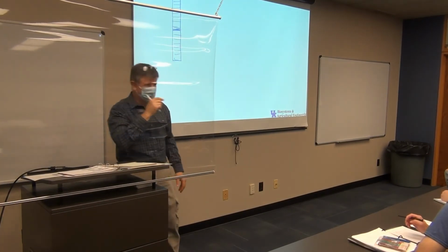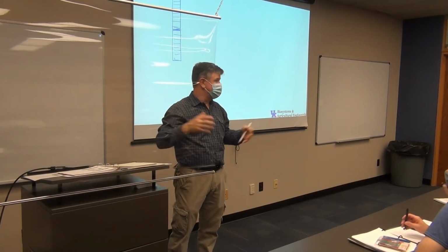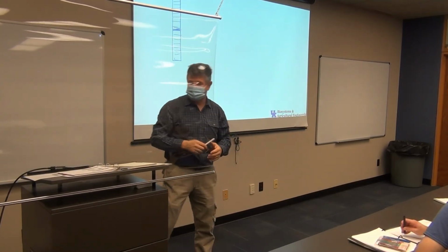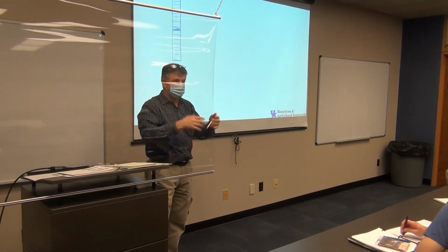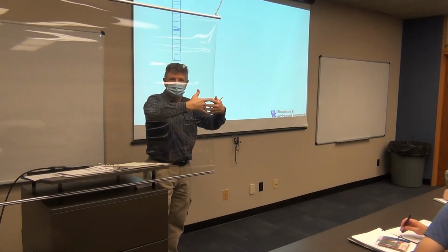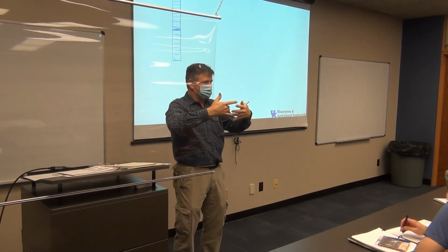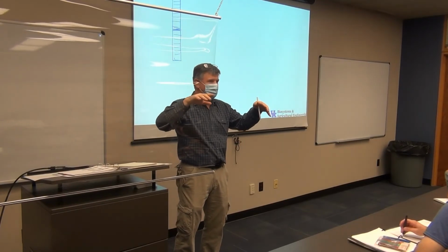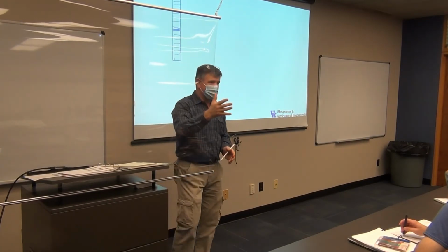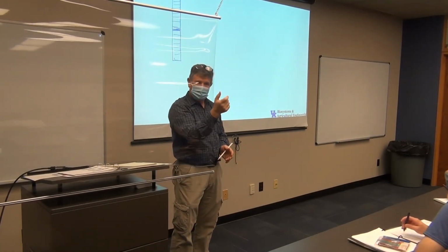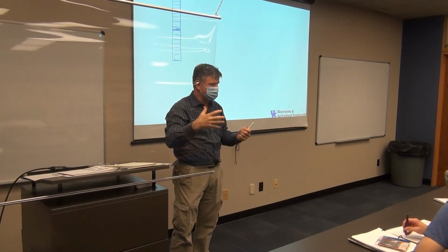And I suggested in there that a lot of these are not going to be perfectly symmetrical, and if we were doing this, we would test a whole bunch of nozzles over and over and over again, and get a variety and all that kind of stuff to really see what's going on. What I suggest for you guys is to flip that and average the two. So what you'll come up with is a symmetrical pattern, okay? It would be kind of a cheap way of doing tests over and over again to get a real average of what it is. So just take this pattern, flip it, put it right here, average those two together, and then you'll get the actual pattern that you work with, one that's symmetric and that you can work with mathematically. Okay, does that make sense?